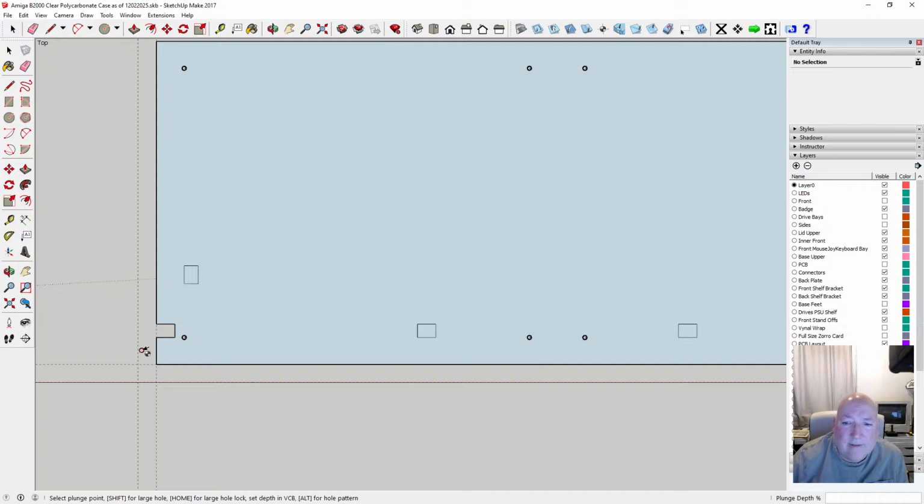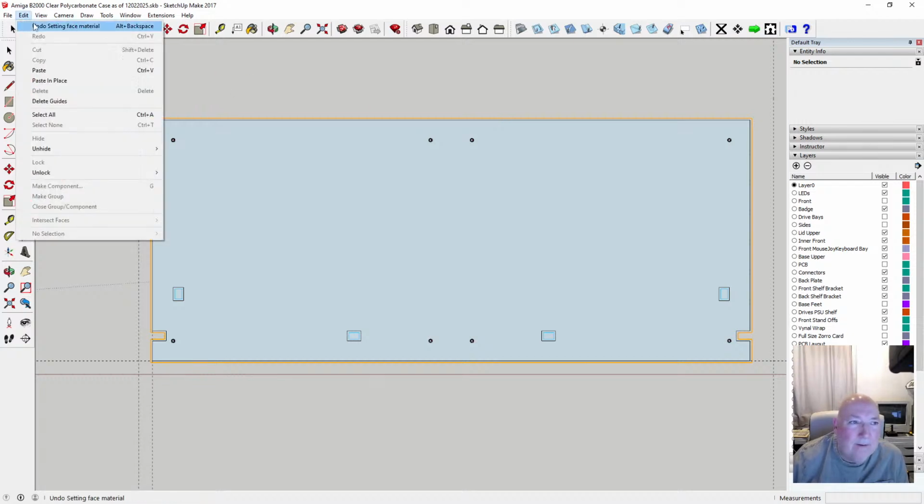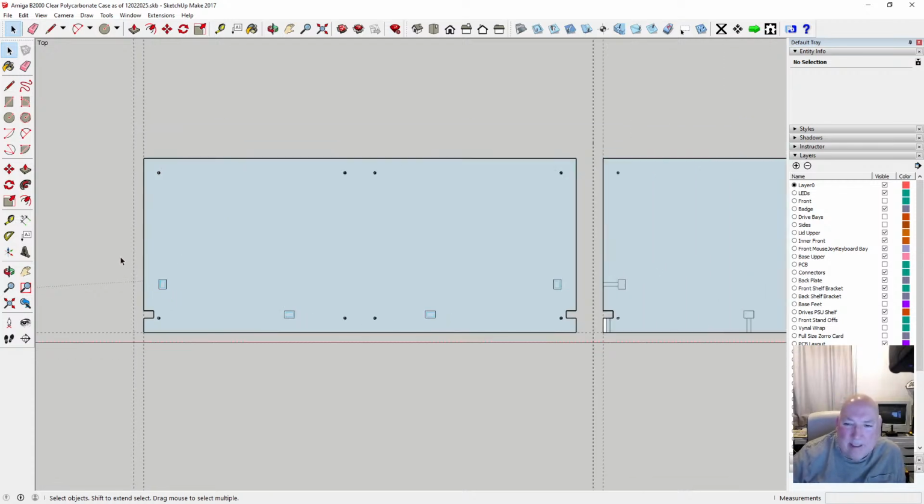Right, so we've done the plunging. Now we're going to do the inside cut. So inside cut, inside cut, inside cut. Now we want the outside cut there. No, we don't want the outside cut. We don't want the outside cut at the minute, because if we cut that out, we haven't pocketed it. We don't want the piece. The material needs to stay clamped down until it's ready.